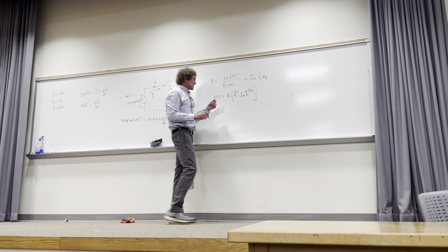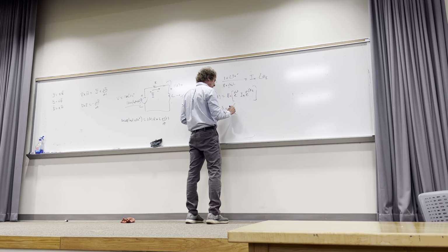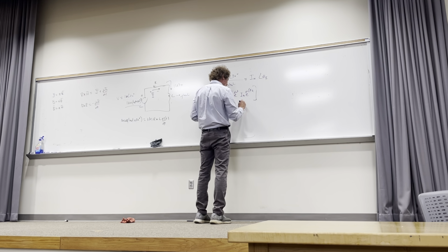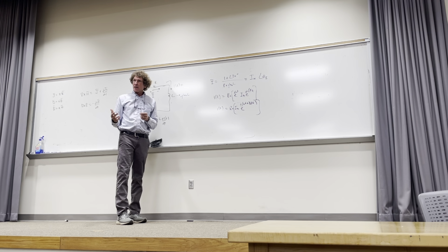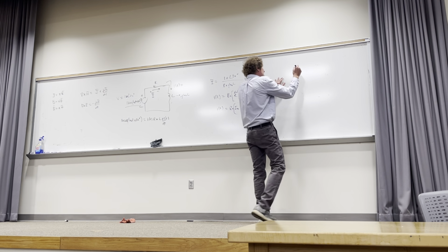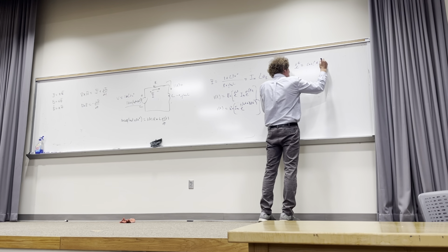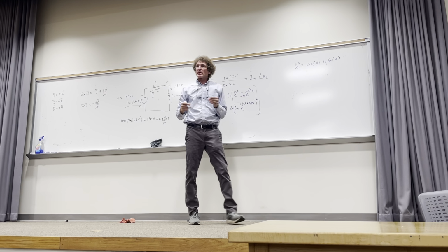Now, the next thing is when you're doing this, you see that I of t here would be equal to the real part. Im is a scalar. And now I add these exponentials, and I have e to the j quantity omega t plus the angle theta I, whatever the angle is. Y'all agree with that? Now, anytime I have e to the j anything, I use Euler's identity: e to the j theta is cosine theta plus j sine theta. Do y'all remember that, class?